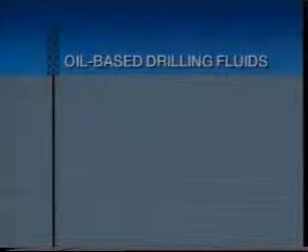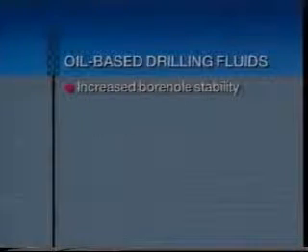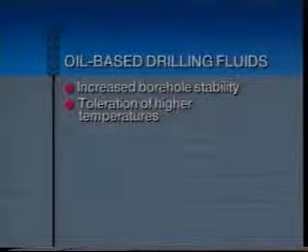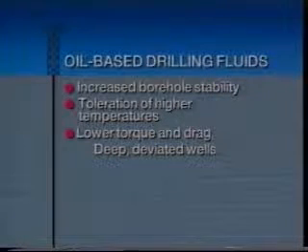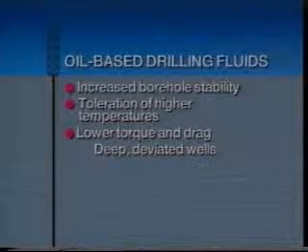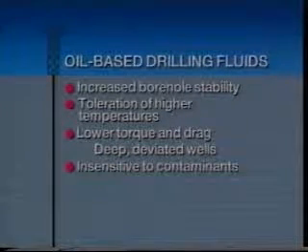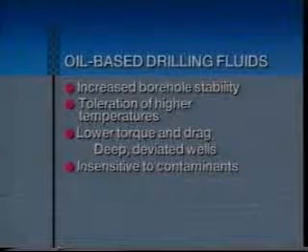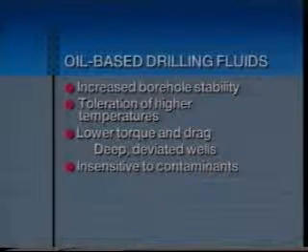The primary reasons for using oil-based drilling fluids are increased borehole stability, toleration of higher temperatures, and lower torque and drag. These factors become important in deep holes and directionally deviated well bores. Oil muds are generally insensitive to chemical contaminants which affect water-based fluids.